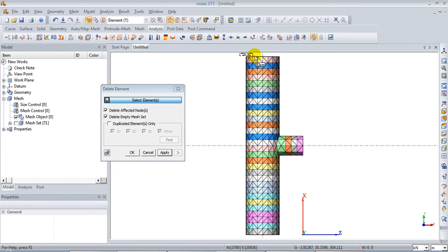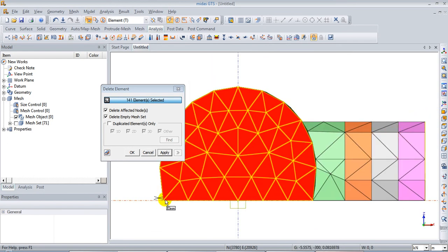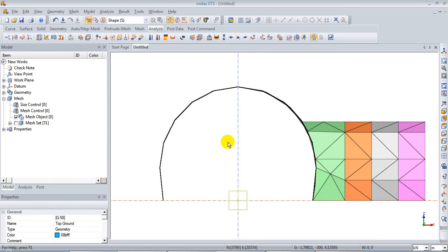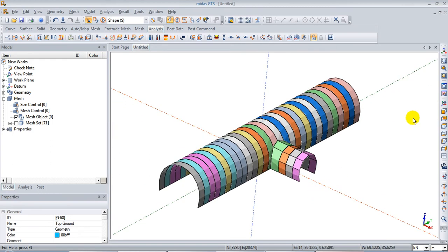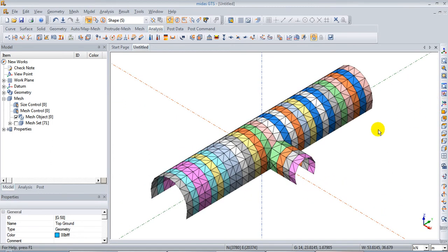We're just going to delete the plate elements at the end, the faces and also the bottom, and this will give us a shell. So that was all quickly and automatically created. So you see there we actually have the shell now, and that is the shotcrete, and that will be very important when we carry out the construction stage analysis and the construction stages, the creation.